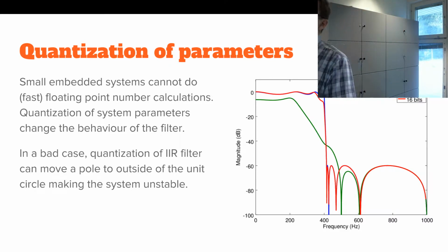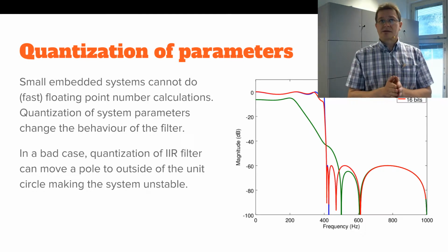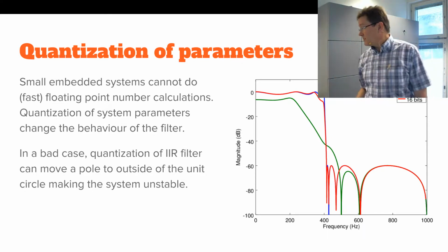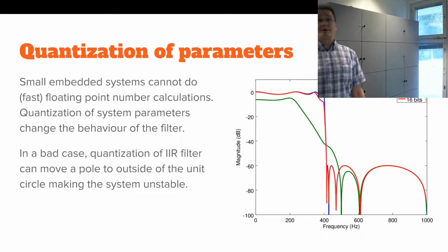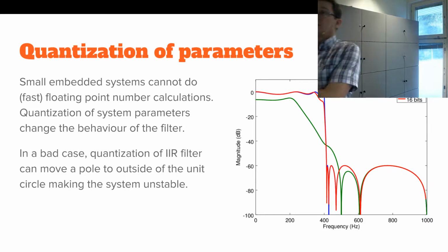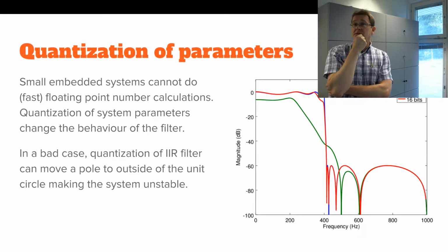But when you are actually starting to quantize the parameters on multiply-accumulate cycles, meaning that you are not using the parameters as they are, but the closest rounded number to a certain precision. And that's a picture of what happens to this same filter. It might be elliptic, or, well, it doesn't matter. It's an 8th or 9th degree filter.